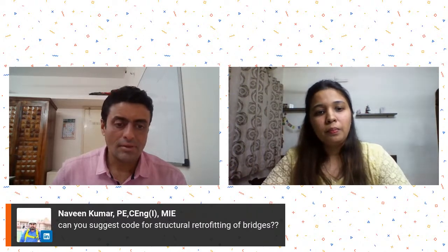Ajay ji is asking which theory is used for analysis of bridges. Right now, I think the analysis is all FEM based, matrix-based analysis methods, using elastic theory. Inelastic analysis is not yet done for major bridges, though for some critical bridges they are doing inelastic analysis also. But usually elastic analysis is followed.